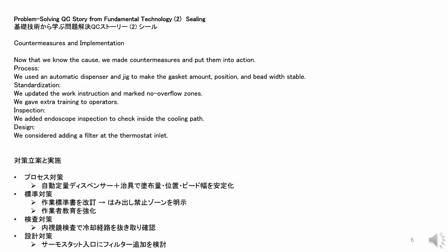Inspection: we added endoscope inspection to check inside the cooling path. Design: we considered adding a filter at the thermostat inlet.